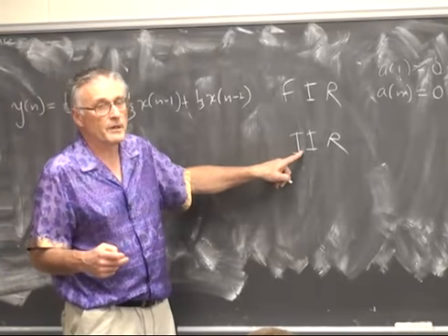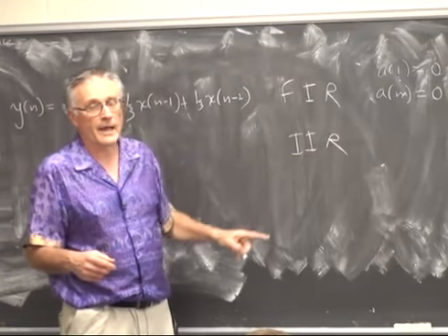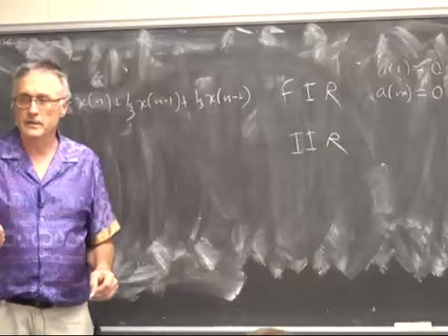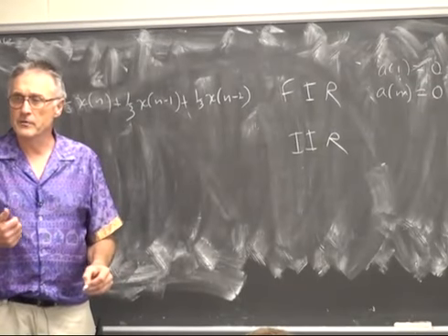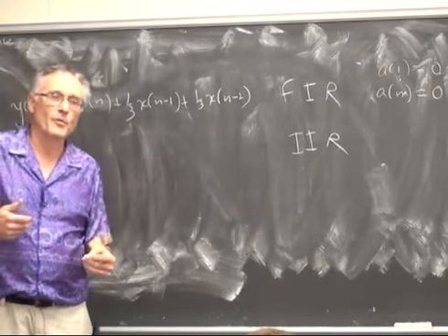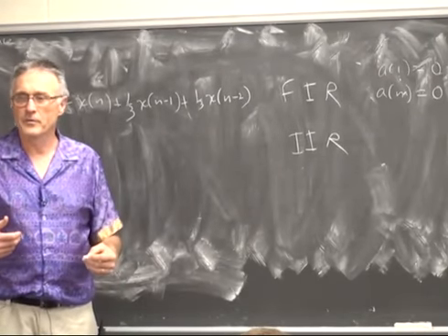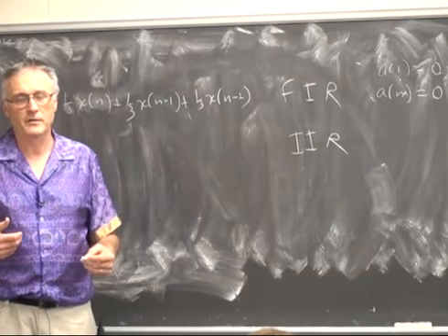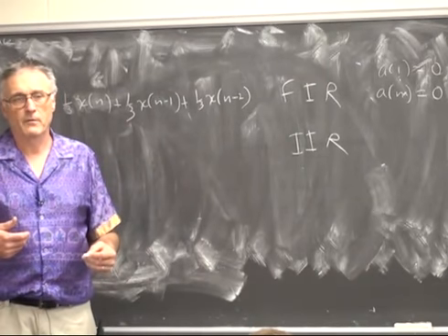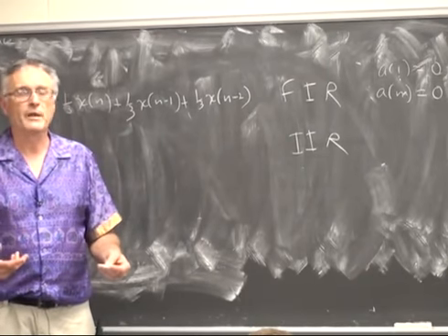Infinite impulse response filters act more like their analog equivalents, and so there's a certain number of engineers of my age who feel more familiar and comfortable with infinite impulse response filters because they're like the filters we used to build with op amps.